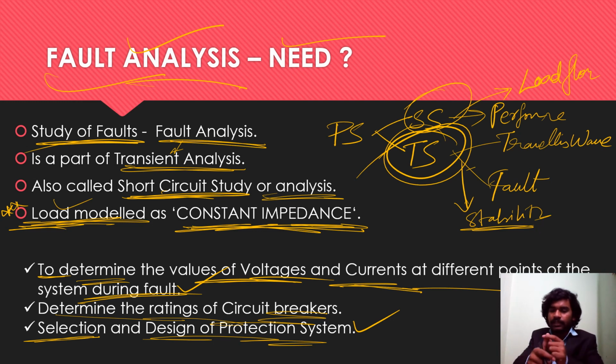For example, if there is something wrong on your hand or your finger, we usually apply some ointment, or you take medicines so that it naturally cures. But in a power system, you have to cut your finger. That's the only thing you can do in a power system. If something goes wrong, cut it. Cutting in the sense you have to do switching action, and the switching is done by the circuit breaker. It switches the power system during the fault conditions as well as the normal conditions. We will see how this happens in other lessons.